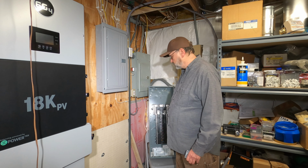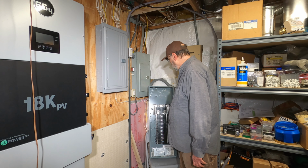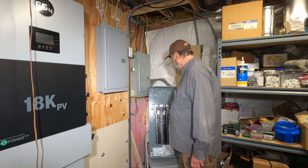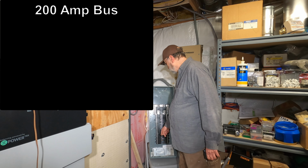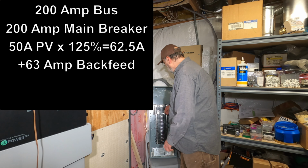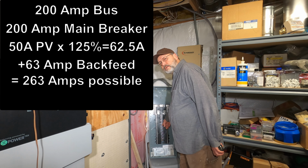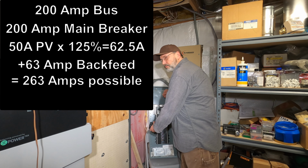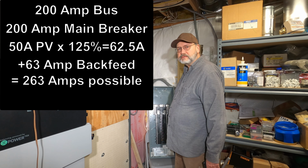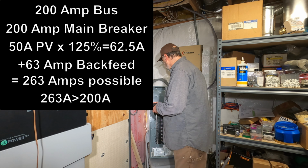So theoretically, it's possible that you can have big enough loads on this bus bar that the current coming in here, we'll say this is a 200 amp bus bar, if you have a 200 amp breaker here and you have 62.5 amps coming in here, and you try to pull 250 amps on this 200 amp bus bar, you do have enough power supplied in to do that. You're overloading the bus bar, and that's a code violation. So that's the point of why I'm doing this in the first place.